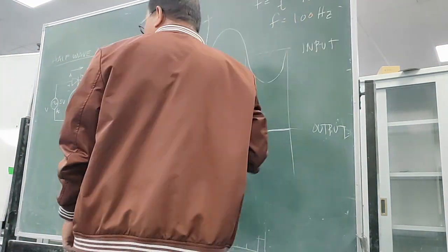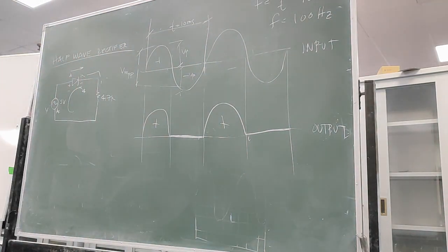And if we have a frequency, you can find the time. But the problem, our oscilloscope will give you only the time, not the frequency. Okay? Our oscilloscope will give you the time only. The time travel, the equivalent time. There's no frequency there. So you have to calculate the frequency based on the time. Got the idea? Alright?